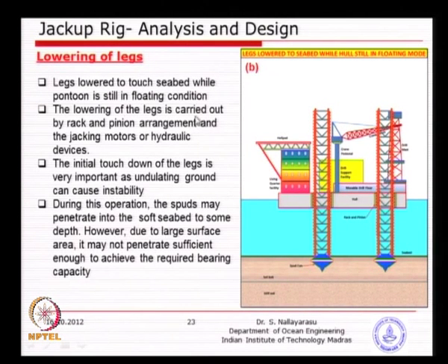As soon as the legs touch down, you need to make sure that all of them touch down at the same time. Suppose you have two of them touching and one of them is still not touching, then you need to make sure that it touches before you start moving up, because that is the time more load will transfer to the legs.